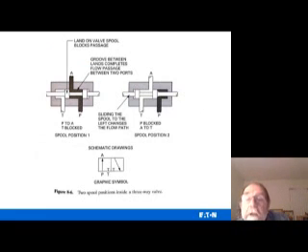Here's one here. This is a 3-way 2-position. You can see here's your tank, and there's your pressure. Then there's your output A, and it's going to show you whether, right now this direction it's working this way. So essentially it would be in this position here. And in order to get the fluid to go up, it has to shift over here to the left.